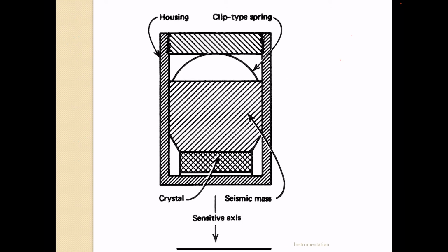Next is the piezoelectric accelerometer. This accelerometer employs the concept of piezoelectricity, where in a piezoelectric material, voltage is generated when it is stressed. So we can see here that the crystal is attached to a seismic mass. This is the seismic mass.